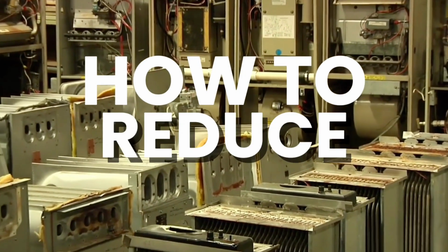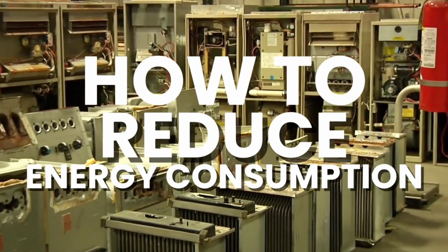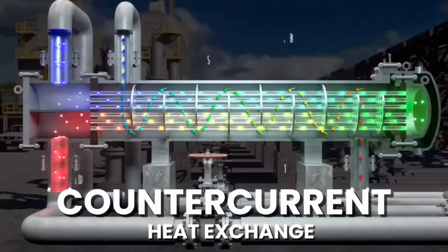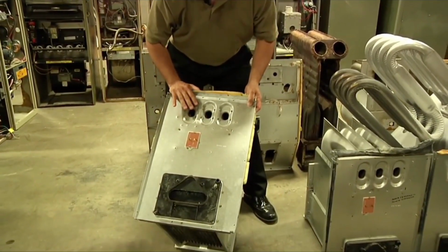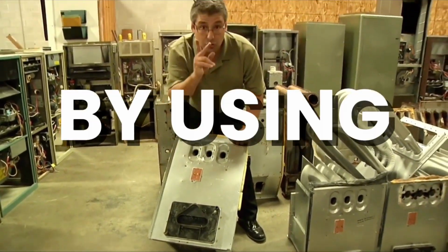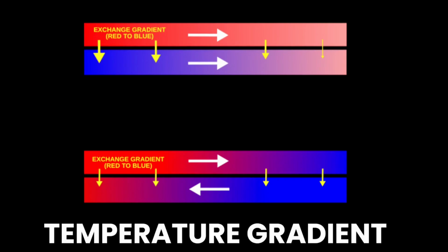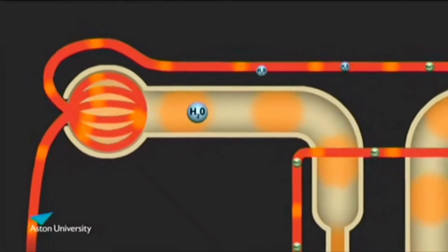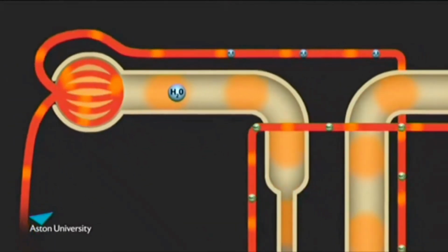How to reduce energy consumption in our heat exchange machine? We can start by opting for a countercurrent heat exchange method. This improves efficiency in heat transfer by using the principle of temperature gradient. In countercurrent, the fluids move in opposite directions, where the hottest fluid meets the warmest outlet and the coldest fluid meets the coldest outlet, creating a steady, high-performance gradient along the entire length, which gives efficient heat transfer. And this is why co-current is used in nature such as...